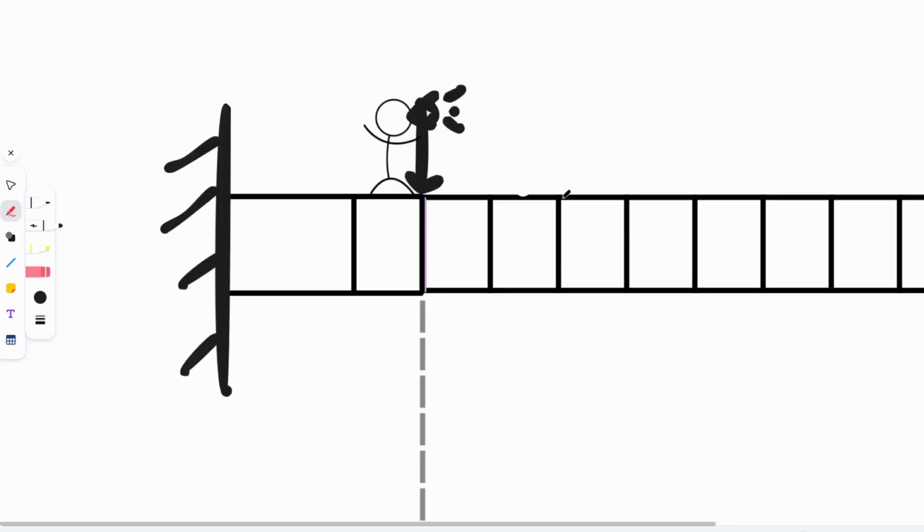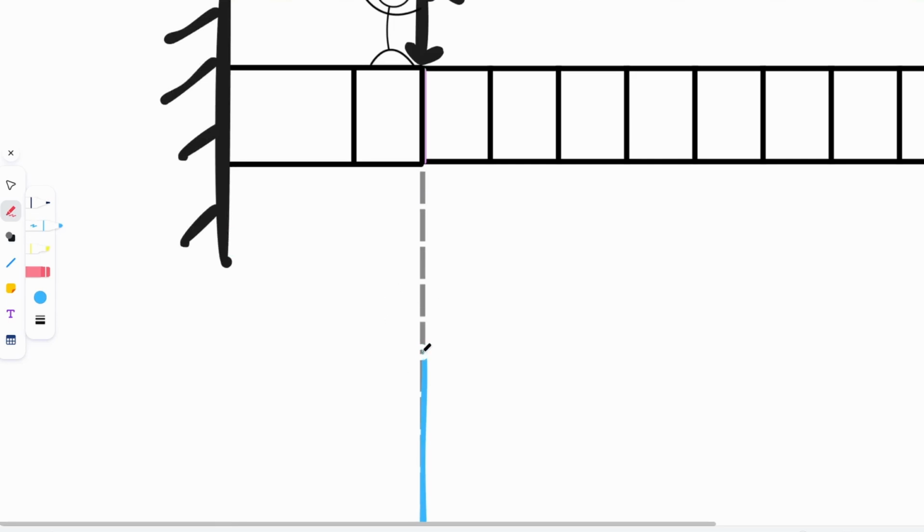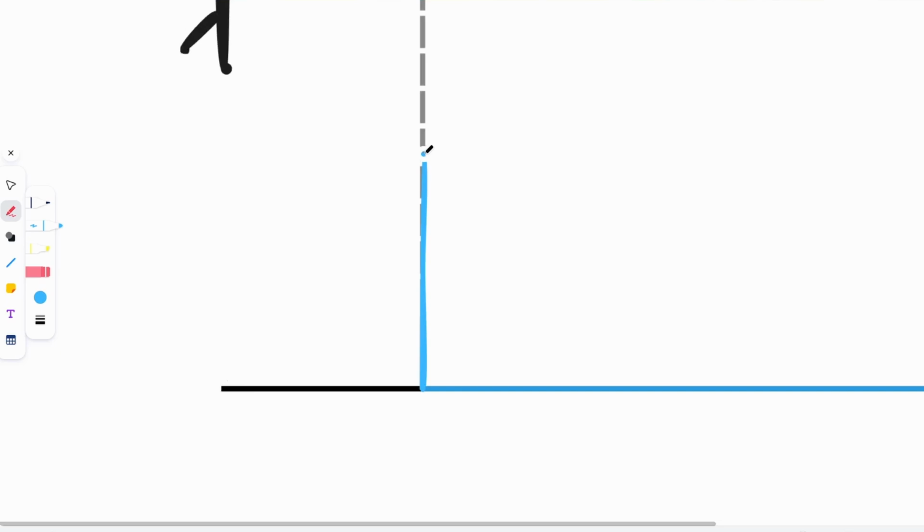And now from the sign convention that we just learned, we can see that we are over here. And so this shear force is essentially trying to move this element downwards. Right side downwards means a positive shear force. And so the shear force will look something like this. And then it will continue till when? Till the last point over here. So it will continue till here.